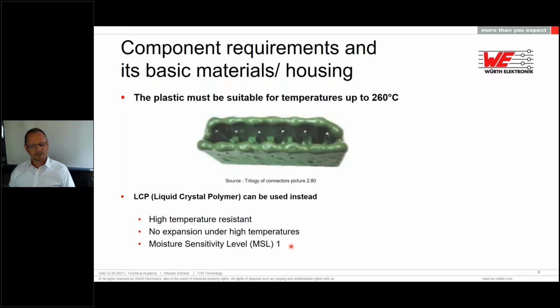That means LCP plastic does not tend to absorb much humidity out of the air. So you can store it as long as you want, and you don't have to pre-bake or pre-dry it before you use it. So nothing can happen here.